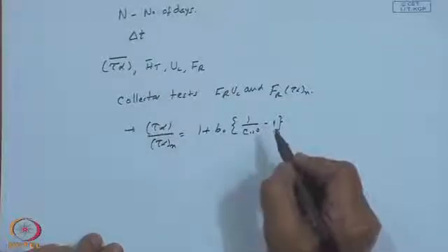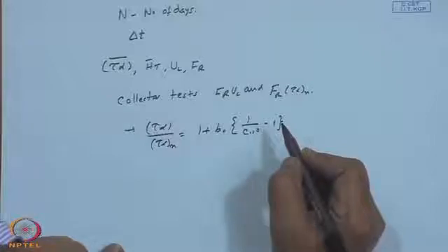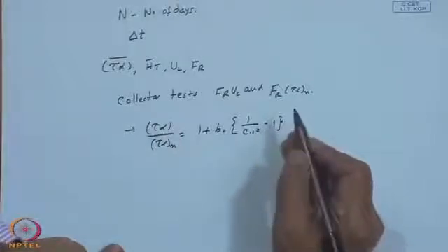You have the effective angles of incidence for the direct radiation in the form of a graphical representation, and the effective angles of incidence for the ground reflected radiation and the sky diffuse radiation, which are constants, they do not change with time, they are a function of the slope beta only, that is your theta g and theta d. So, one can estimate your tau alpha bar as per the relations which we have already dealt with in detail.